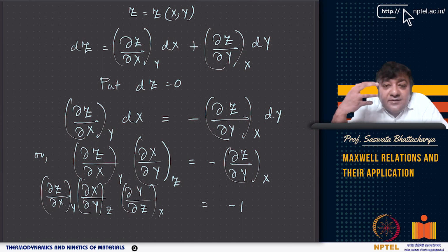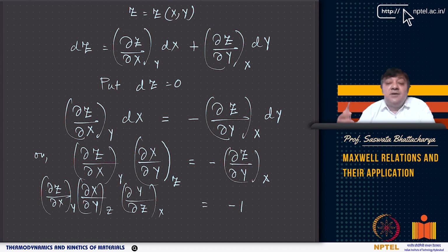Now think of Cp and Cv, like heat capacity at constant pressure or constant volume. These can be measured, as we have already discussed, by calorimetry. And then you have alpha, the volume expansion coefficient, meaning the thermal expansion coefficient, the change in volume with respect to temperature. It can be related to the linear thermal expansion coefficient, and this can be measured using something like dilatometry. And then you have beta, or kappa T, kappa S. These are isothermal compressibility and adiabatic compressibility, which can also be measured, right?